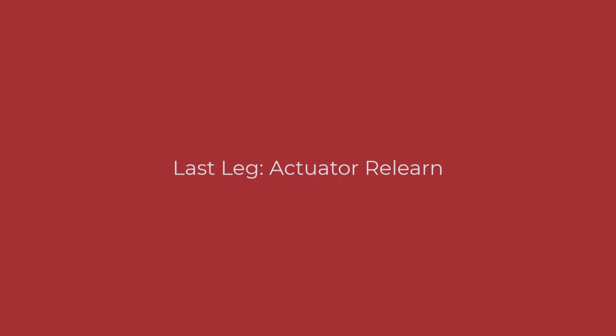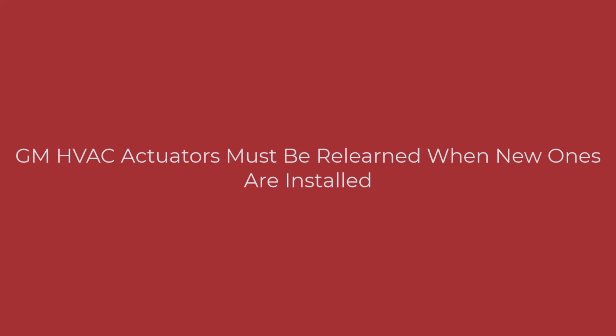For this last segment, I'm going to have you go through a blend door actuator relearn procedure. On some vehicles, particularly GMs, the blend door needs to be indexed by the HVAC module itself. What I mean by index is that the HVAC module needs to learn where full open and full closed are for that blend door when we install a new one. The actuators on the GMs can rotate 360 degrees around, but we don't need them to move that far. We just need them to go full open and full closed. And the module can only learn that if we force it to relearn that procedure.